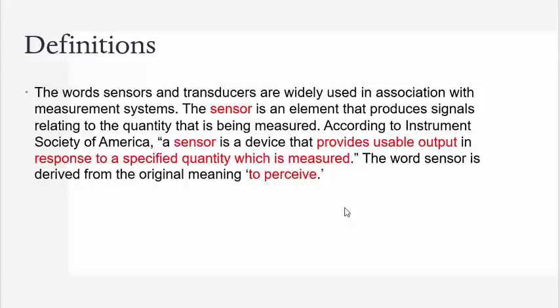The output signal can be any measurable signal and can generally be an electrical quantity, as an example. Basically, sensors are devices that perform input functions in a system as they sense the changes in a quantity. Coming from the word sensor, they sense the changes in a quantity. The best example of a sensor is a mercury thermometer, wherein the quantity being measured is heat or temperature, and the measured temperature is converted to a readable value on the calibrated glass tube based on the expansion and contraction of liquid mercury.